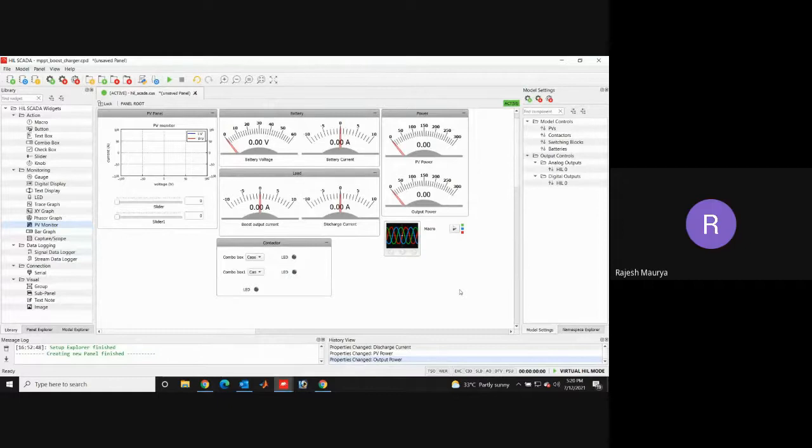Actually, you need to design your controller and you need to apply BMS, battery management system, onto that part. It's a kind of simple controller, designed in a simple way that it happens in this way. But in that case, you need to design a separate controller for that, and you need to charge and discharge the battery. Here, what I have taken, I have not read the SOC of the battery. I've just turned the boost on and off.